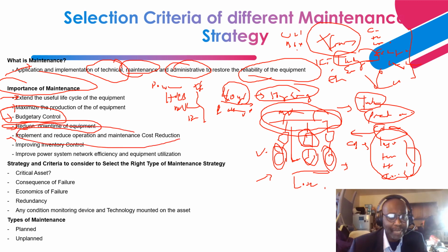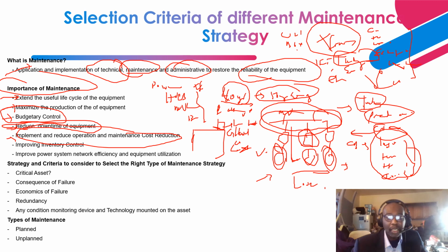Like I made mention, if you are able to implement all these maintenance strategies, for instance, condition-based maintenance, where for a transformer you have a bushing monitoring device that provides, on a real-time basis, the bushing monitoring parameters, that is capacitance and tan delta of the C1 section, capacitance and tan delta of the C2 section, then the leakage current and the wattage power loss due to leakage current flow.